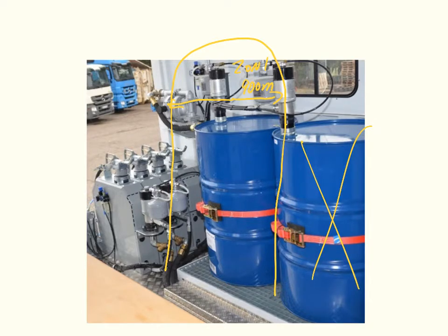And then what we do is, outside of that, of course, we have a Zone 2 location, and that Zone 2 location extends outwards like so. And that comes up 450 mil from the floor, and that is a Zone 2 location.